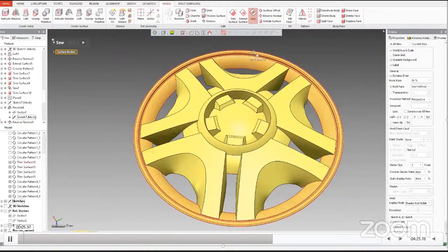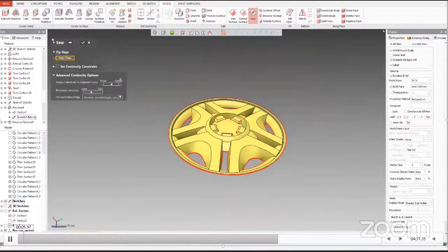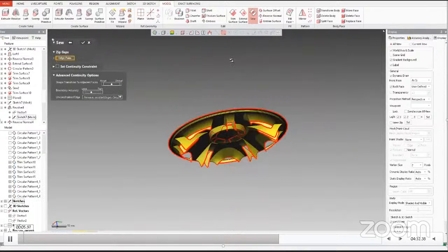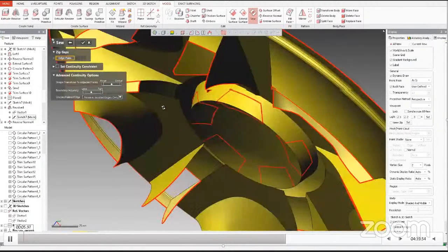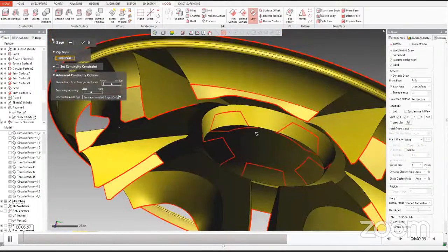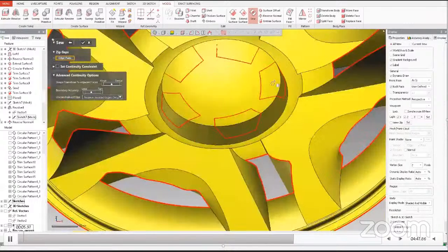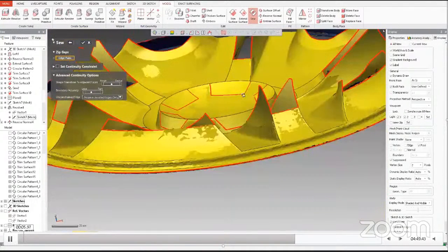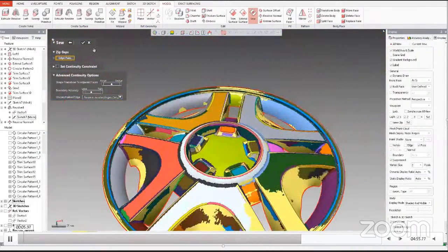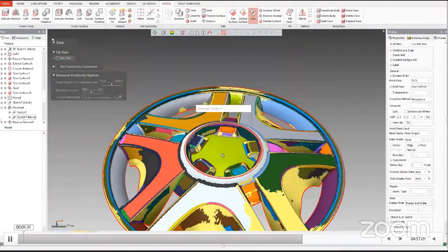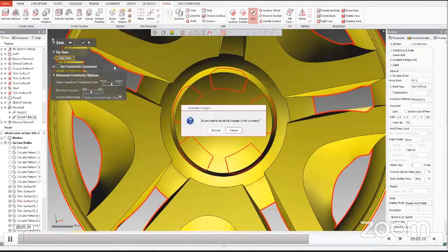So there are some touch-ups left in the final results. We want to sew these, stitch them together, and we can see at the bottom there are some extended walls and the profiles, and we can also see in the middle there are some boxes which are intersected with the surface. So we have to perform the trimming operation there. So just close the stitching command here, and then, since it is also intersecting, we cannot apply the stitching command here. We have to perform the trimming operation first in the middle.